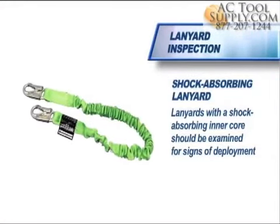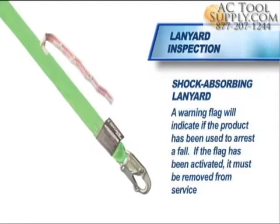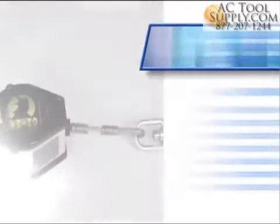Lanyards with a shock-absorbing inner core should be examined for signs of deployment. A warning flag will indicate if the product has been used to arrest a fall. If the flag has been activated, it must be removed from service.